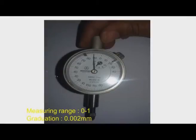Now, we have another dial indicator. This measuring range is 0 to 1 millimeter, and the resolution is 0.002 millimeter. So, for one complete revolution, we can see here it is 0 to 100 and again 0 to 100. So, for one complete revolution, the smaller pointer will indicate 0.2 millimeter displacement.